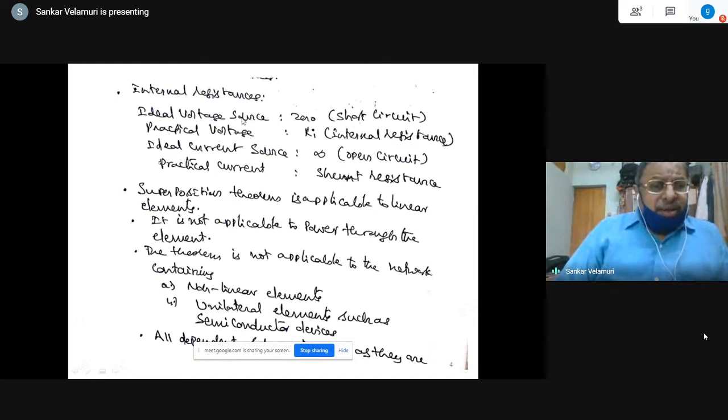Of course, now I got the idea to explain about the AC sources. Ideal voltage source, of course, is 0. It is short circuit, to be replaced with internal impedances. Practical voltage source is to be represented with Z, resistance or Thevenin, or simply in machine theory, if it is synchronous machine, synchronous impedance, because it is alternator. Or other reactance or impedance.